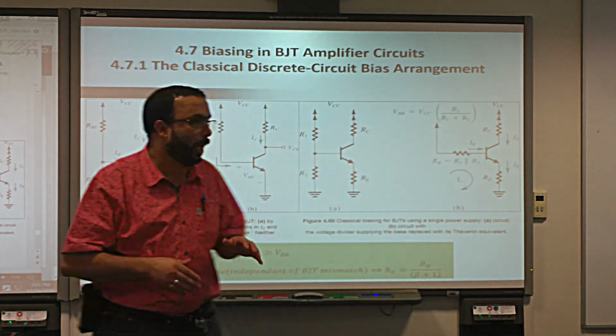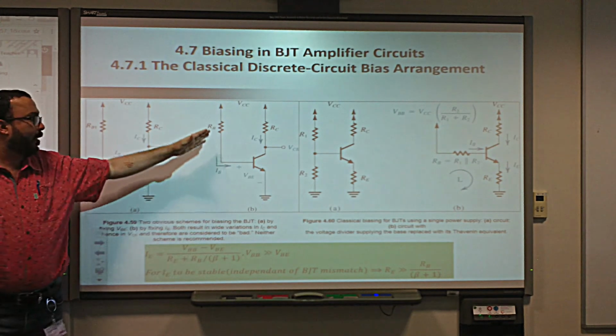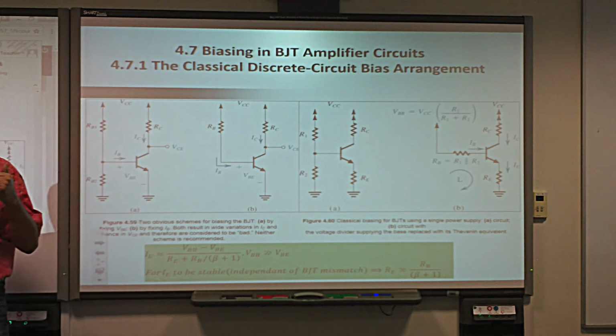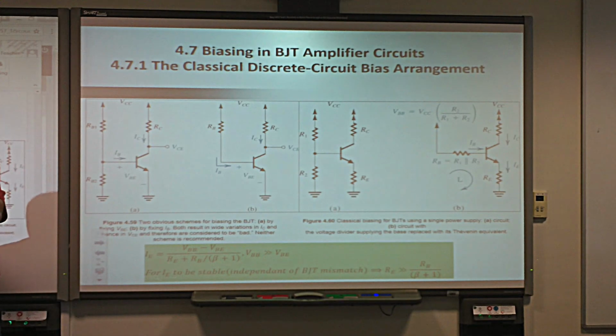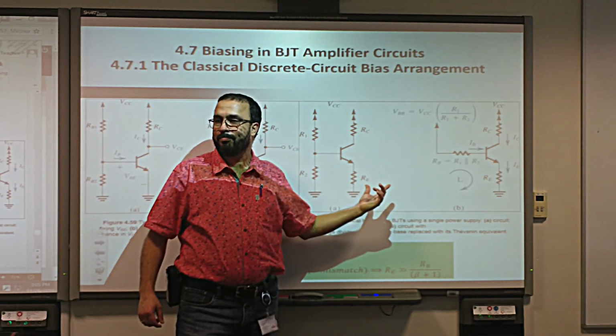Okay? Very good. So this is the first way, to fix the base voltage in here. And this is similar to fixing VGS. We said this is not a good one. So the best way is to do what? Is to place an RE at the emitter here.